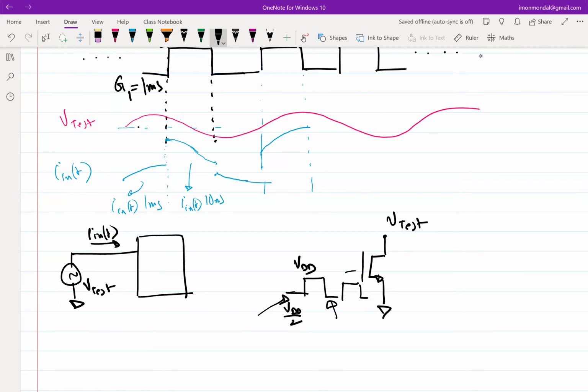Okay. So if I take the example that Vasudev suggested, when you have the input to be VDD by 2, maybe you have some R_on. When it goes to VDD, it has a different R_on, hopefully a smaller value. And this on resistance keeps switching between two values, which means I have two different values of G, right?